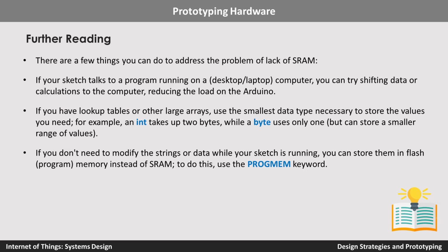There are a few things you can do to address the problem of lack of SRAM. One thing is, if you are using an Arduino and you have another component like a Raspberry Pi or cloud connectivity, then you can shift the data or calculations to the other component which has more computational power and reduce the workload on the Arduino.